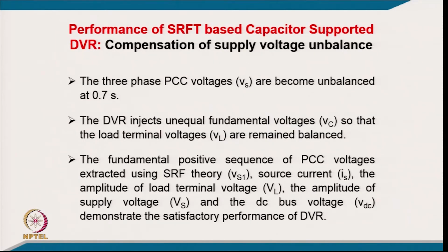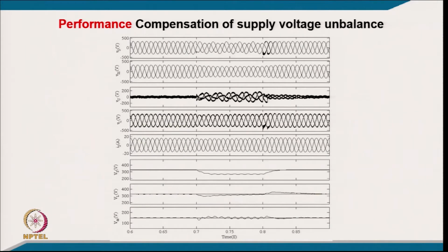So, coming to the performance of this synchronous reference frame theory based capacitor supported DVR for compensation of supply voltage unbalance. The 3 phase PCC voltages become unbalanced at typically 0.7 second, and the DVR injects unequal fundamental voltages so that the load terminal voltages remain balanced. The fundamental positive sequence of the PCC voltage is extracted using SRF theory, and the source current, the voltage amplitude of the PCC voltage and the DC link voltage demonstrate the satisfactory performance of the DVR.